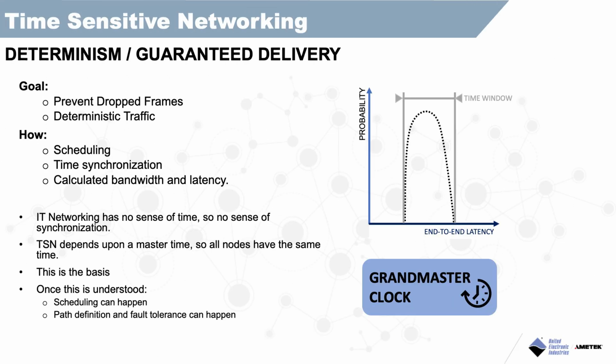TSN was originally conceived to use the Ethernet infrastructure for applications that require deterministic or time-sensitive data handling. Everything from audio-visual systems, SCADA, building automation, and vehicle systems. Now we are seeing use in the aerospace, military ground, and even the space arenas. They all have similar common requirements, which include high availability, guaranteed message delivery, rapid response times. Not only rapid, but consistent response times, precise timing, and synchronized actions.